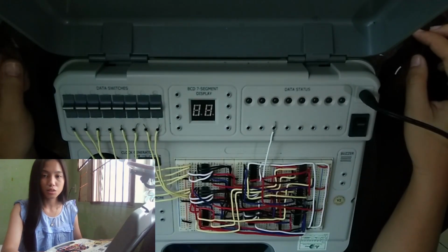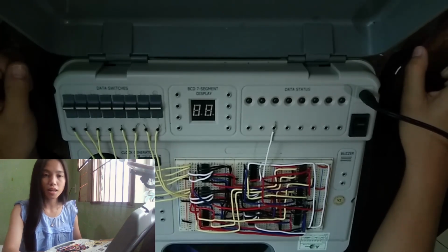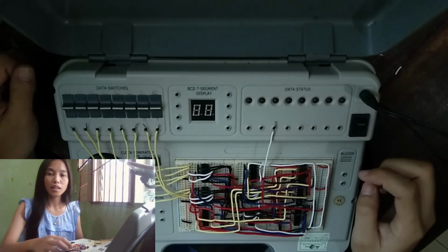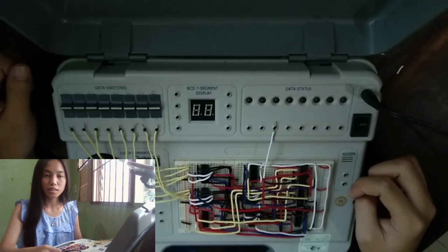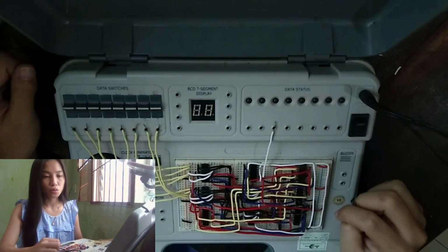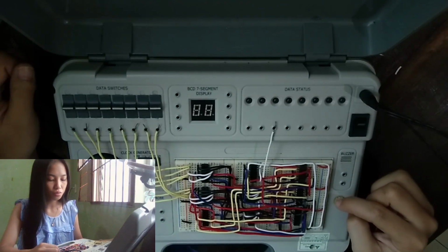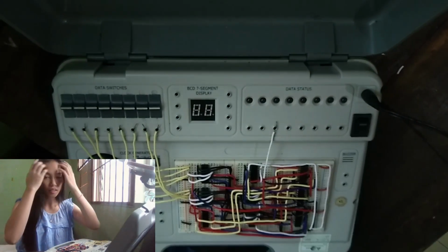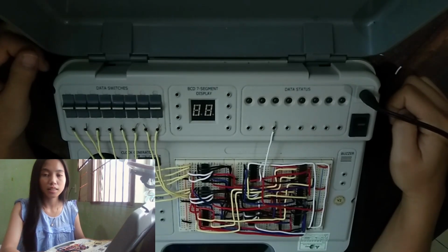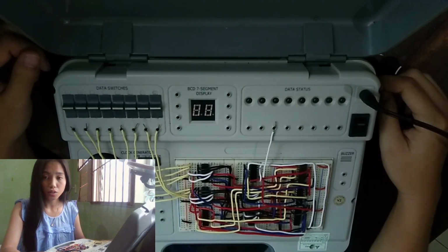Then the 3 OR gates, which is the IC74LS32, 1, 2, and 3, and the 2 NOT gates, which is the IC74LS04, then 1 and 2. So we have a total of 9 ICs. By combining these gates, we've constructed NAND, NOR, XOR, and XNOR gates to achieve the desired